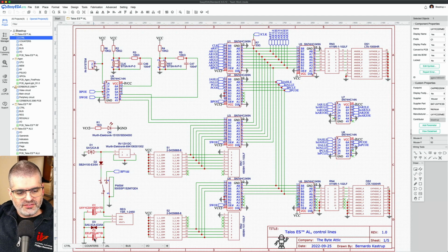But I had used the same capacitor as capacitor C2, and that is incorrect, and the reason is capacitor C2 is on the 5-volt rail, and that's a capacitor with a voltage rating of 6.3 volts. On the 5-volt rail, that's perfect, it's no problem. But this part here, capacitor C1, is on the 12-volt rail, so I can't really use a 6.3 volt rated capacitor there. And I just lazily copied C2 into the C1 position in the previous 2 designs.